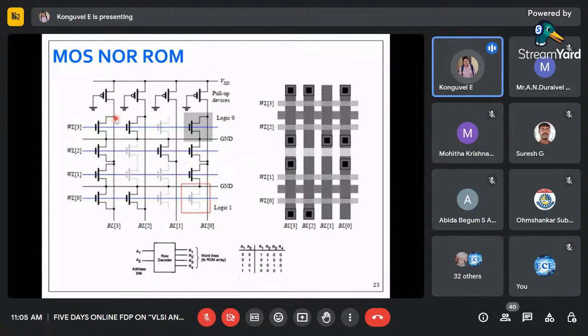See, again, we should have a doubt here. Sir, already here VDD is connected to this line, and again our ground is connected. What will happen? Certainly, we will be having static power dissipation. Certainly, we will be having static current flowing because of that static power. Even though we are having some disadvantages, this topology works fine for our memory. That is why we are using it, right?